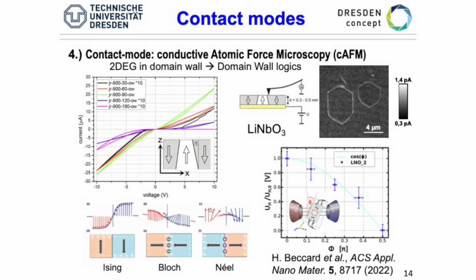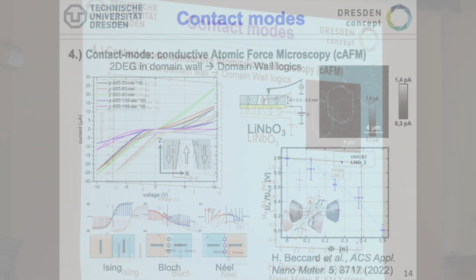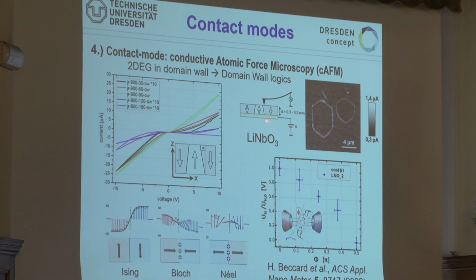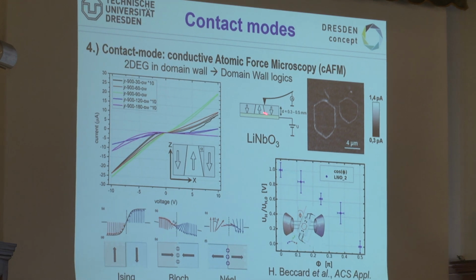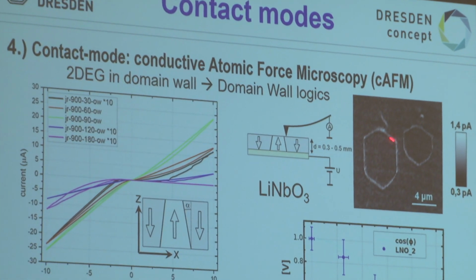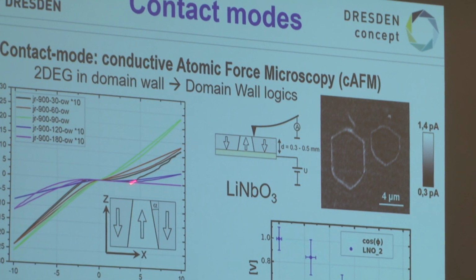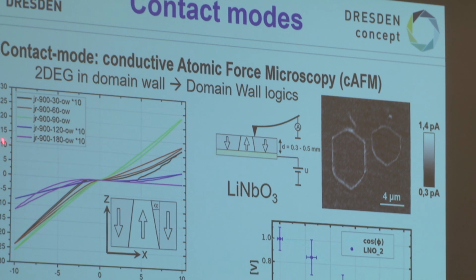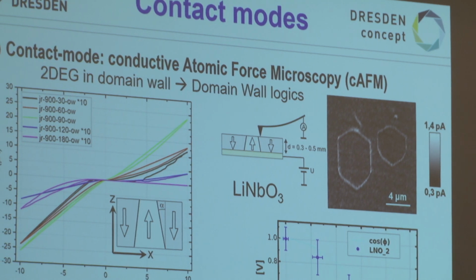If you want to have some knowledge on that, that's actually some research we do exactly with this kind of mimic. We're looking, for instance, at so-called domain walls. We rather had actually the barium titanate before, and if you take basically the section which is in between such two polarizations, it's called a domain wall. Now, funny enough, this can be a two-dimensional electron gas. And in fact, your scanning force microscope operated in the conductive mode can measure that. And you can measure currents with this kind of mimic up to a couple of microamps, even milliamps, per domain wall.